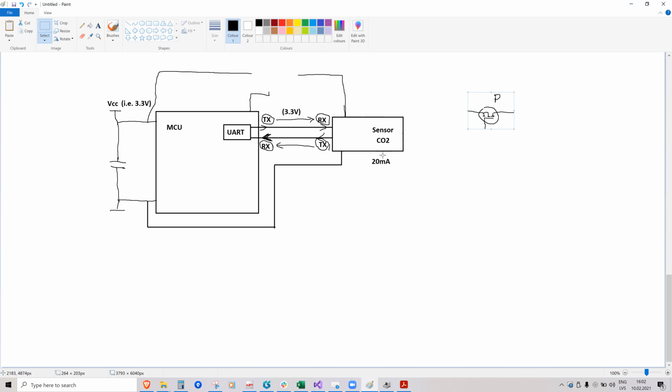What is the reason? For example, you have a battery, you measure the current through the battery, you tell the microcontroller to switch off this P-channel MOSFET, but even with the switched off MOSFET, you see that the current is still 20 milliamps. The sensor is still working. Maybe it has an LED which is blinking, but you don't understand what's happening.